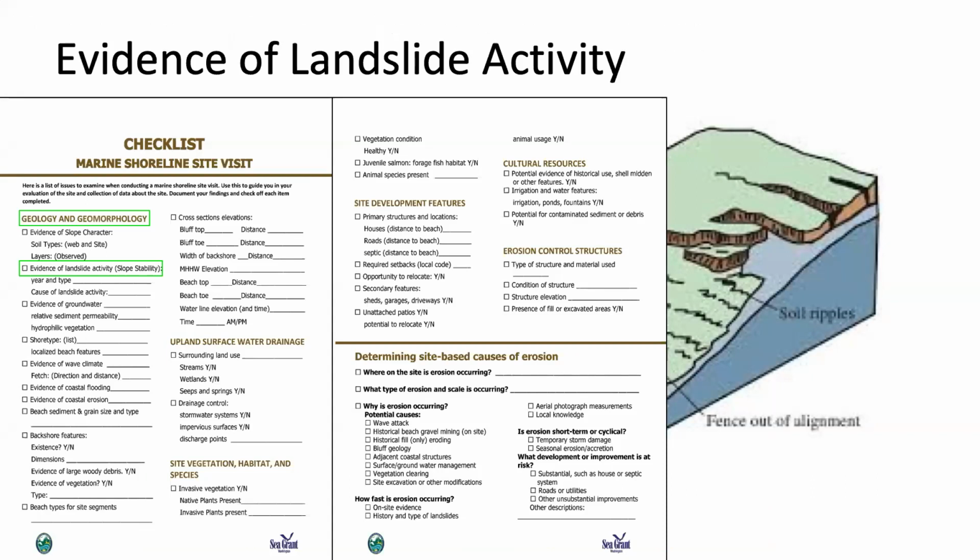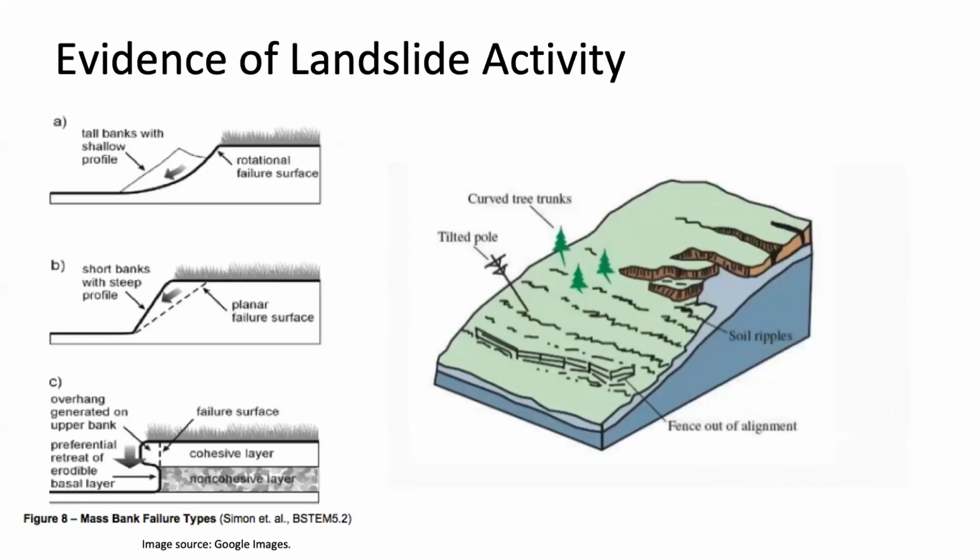There's a lot of ways to characterize slope failure, and depending on who you're talking to, what your expertise happens to be, those might be labeled different ways, but I'm going to stick with 4 particular failure types that you'll see in a moment here as that checklist comes off of there. So let's start with those on the left. The top one there is a rotational failure. You might hear an engineer call it a global failure. Global meaning the shape of that semicircular failure plane there.